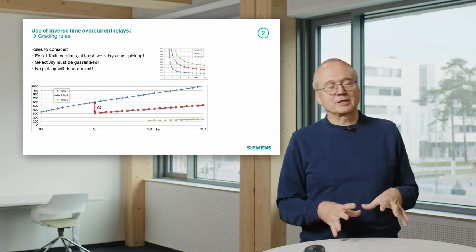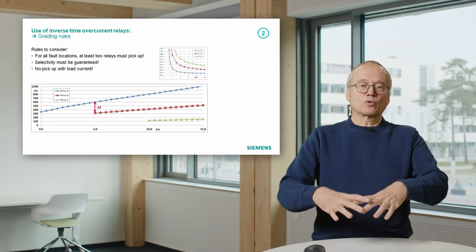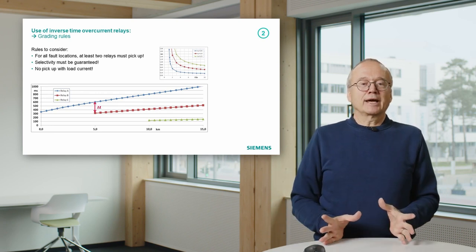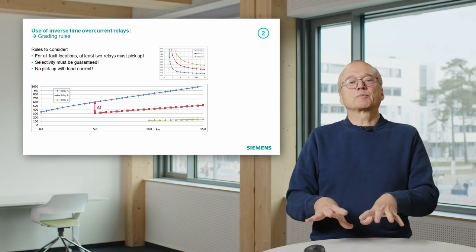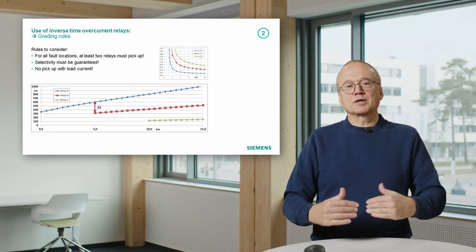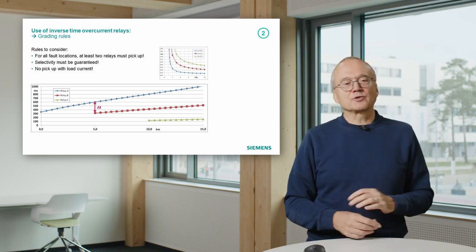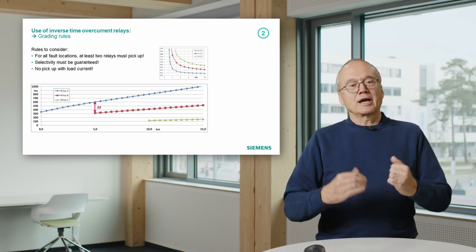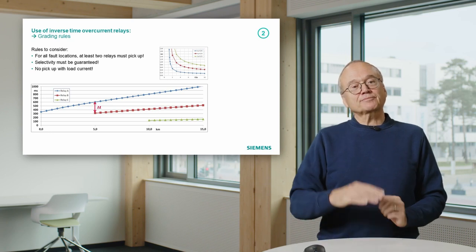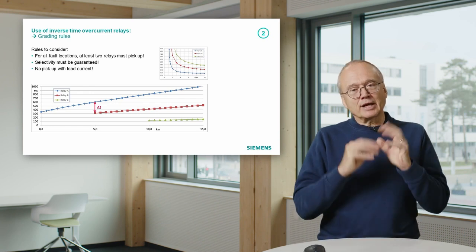Remember, I discussed that example in one of the first videos where you had somehow a blackout of a part of a city which has been without energy for some hours. If you re-energize that, maybe a lot of aircons will be starting then, which have a pretty high current, and your setting should be high enough to avoid tripping with that current. And you can imagine